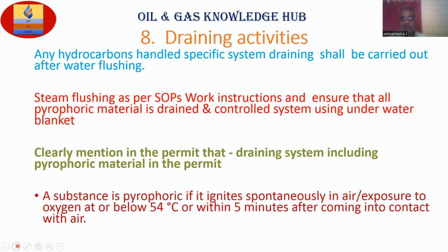A substance is pyrophoric if it ignites spontaneously in air, on exposure to oxygen at or below 54 degrees, or within 5 minutes after coming into contact with air. So this is a very dangerous material, my friends. Whenever you are draining suspected pyrophoric material, you have to open only the bottom bolts.